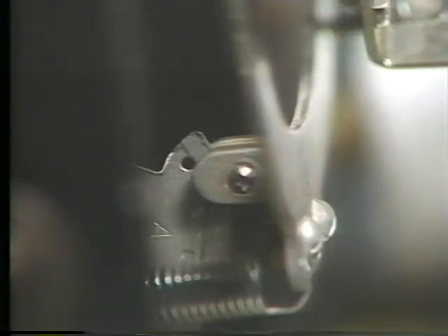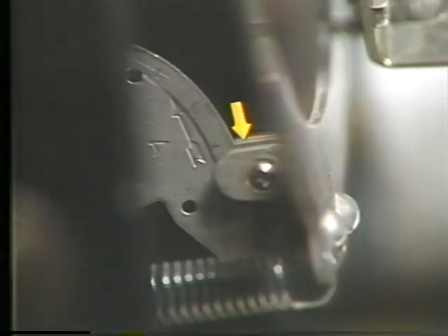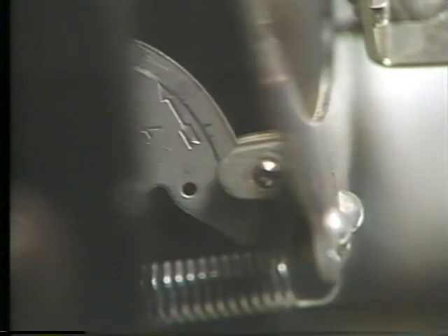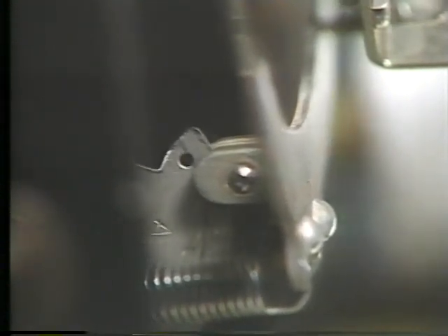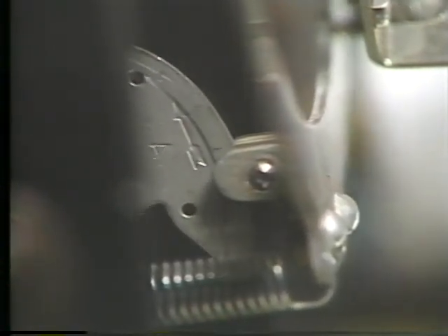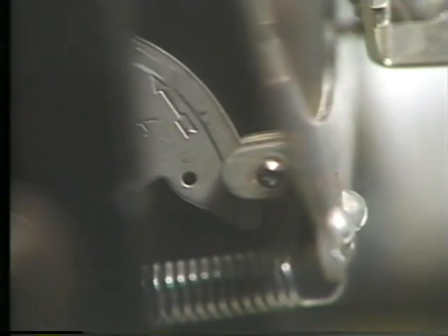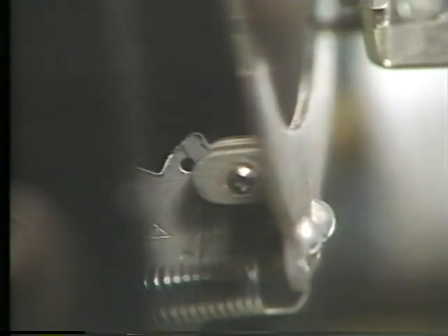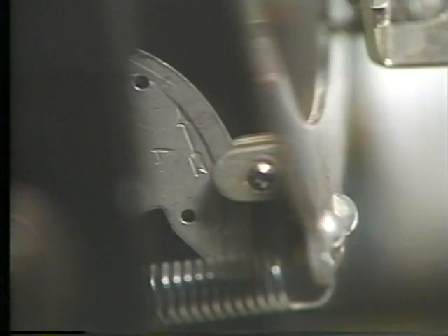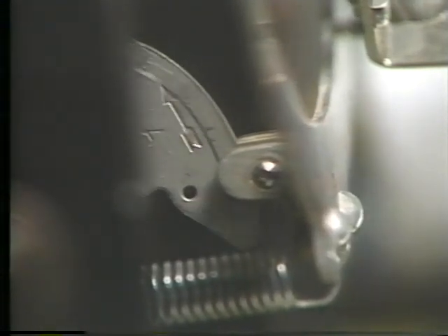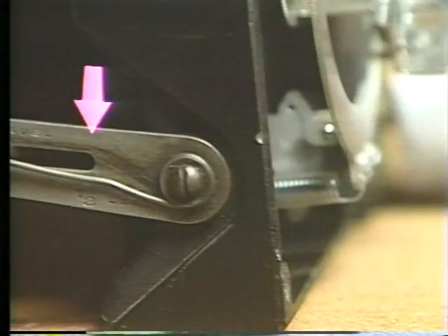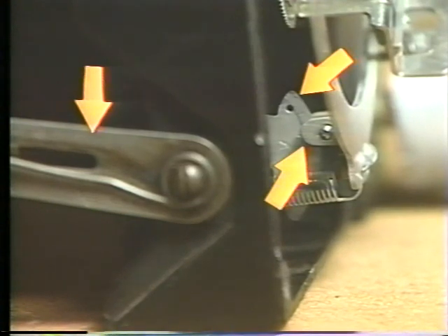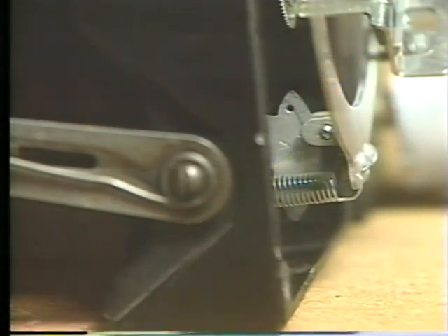When the cam rotates, it pushes against a cam follower. The cam follower in this positioner is attached to the balance beam. So, when the cam rotates, it pushes against the cam follower, which causes the balance beam to move. The drive arm, the cam, and the cam follower make up the balancing mechanism of this positioner.